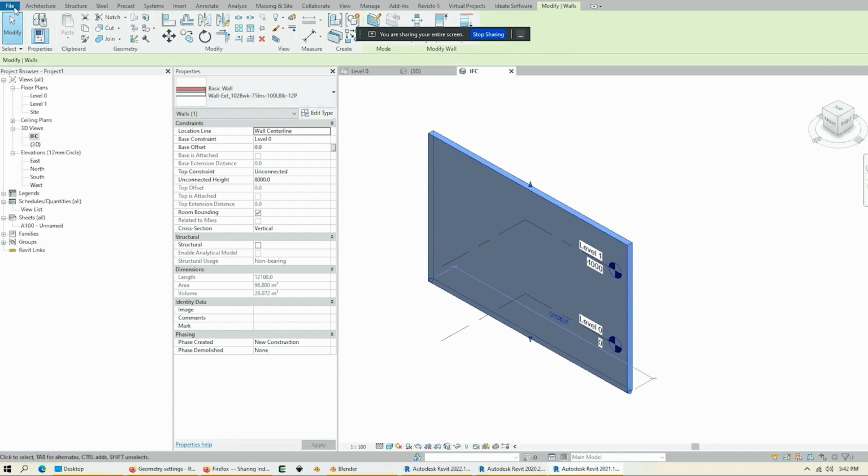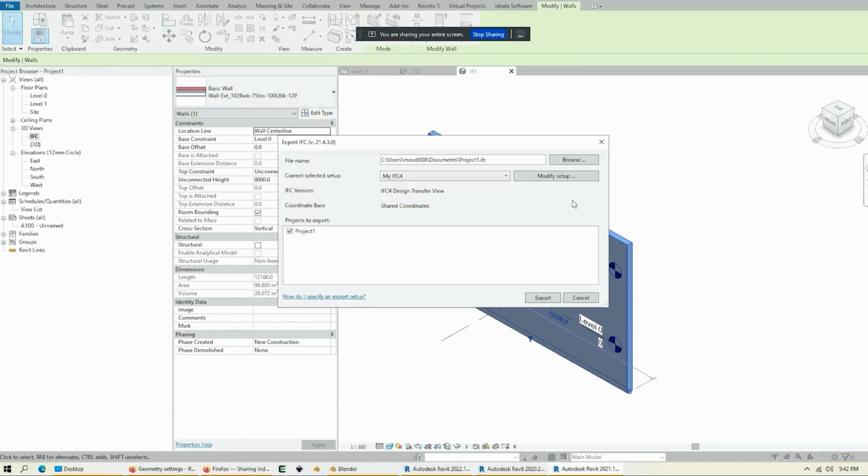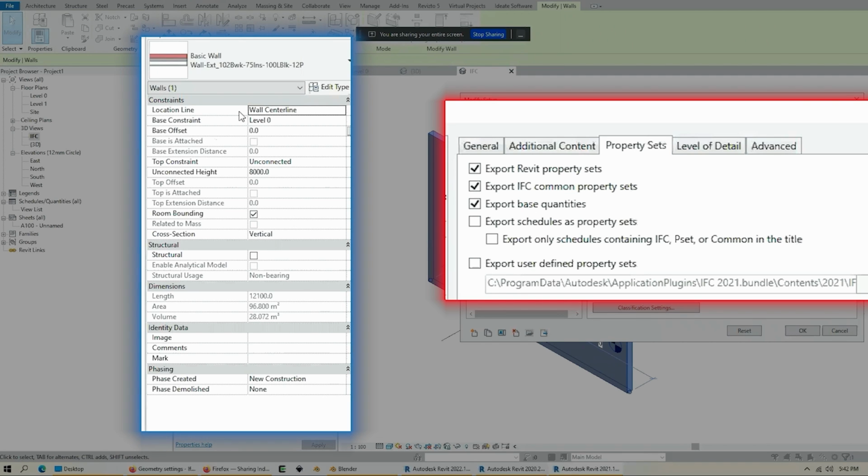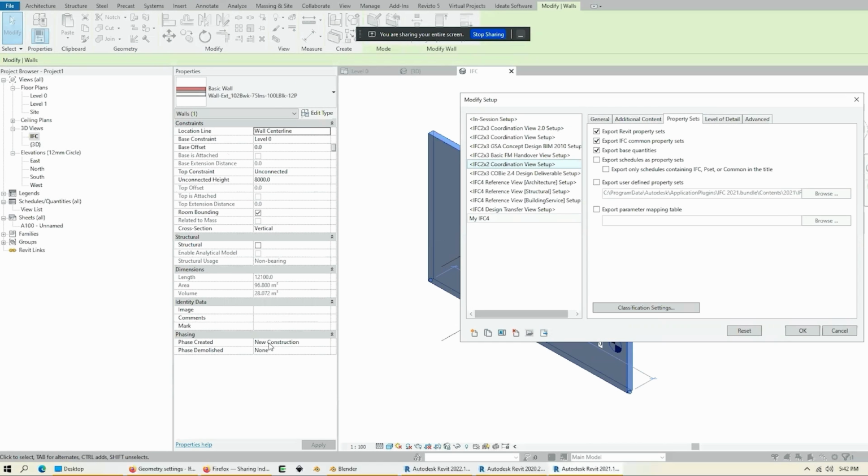And if I have that option enabled, all of this data will come through in IFC. And the only time that's good is if you're dealing with an unknown author and you don't know where they stored stuff. We talked about how the way people store things in Revit is a mess, right? There's no standard location to put any data. People just make it up as they go. They invent new parameters, and every company has their own standard.